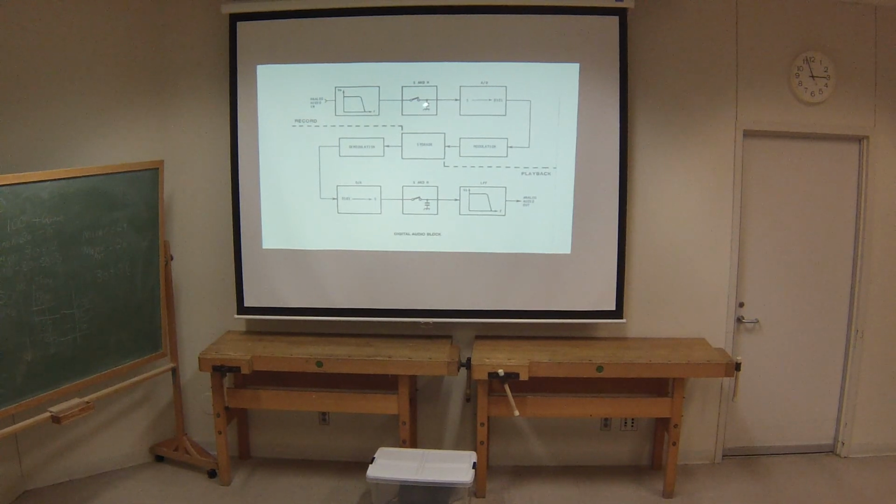So now here's our little capacitor drawn in right here. We come into our sample and hold circuit, and at this point we have our pulses. We go into the actual conversion process where we take the value of each one of those pulses and convert it to a binary number. In this case, we're just showing 4 bits. Actual digital audio is a 16-bit word. So that means that you have, well, I'll get into that in a second, a lot of levels.